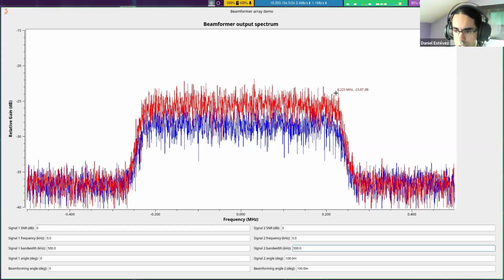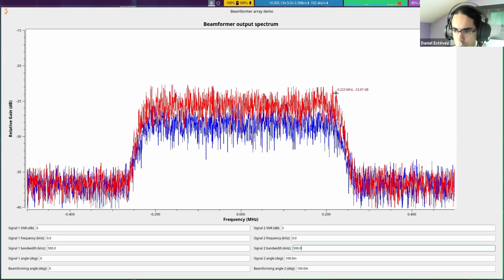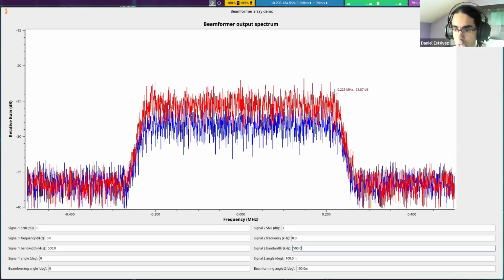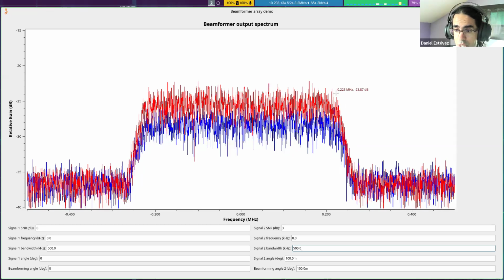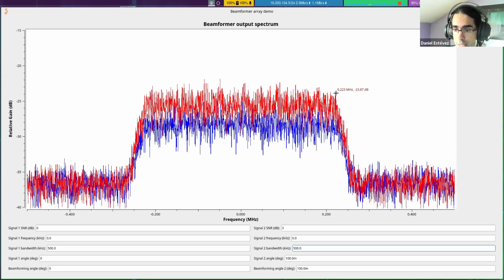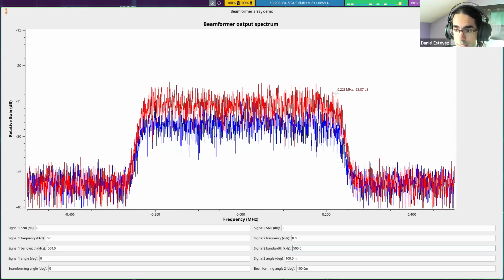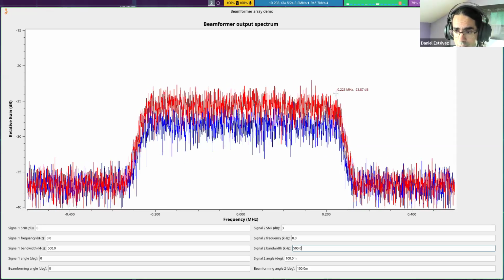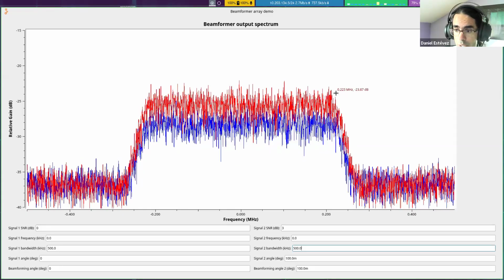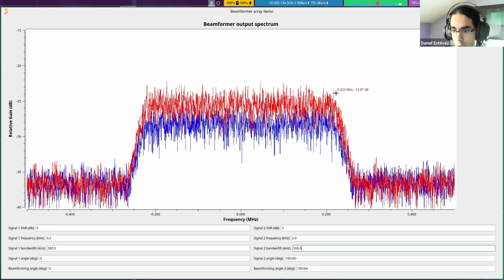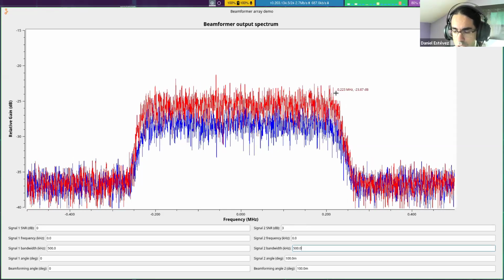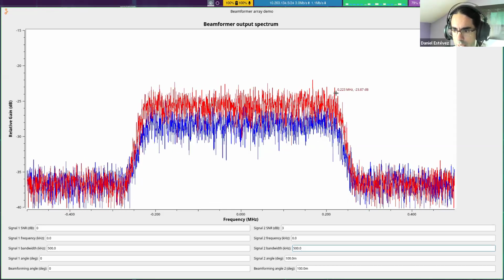So this is something which is quite interesting about beamforming. We can point these beams to just one particular location. Coming back to what Steve was mentioning about your home Wi-Fi, it has all these antennas, and one of the reasons why it has all of these antennas is because it can point beams, and it can point to, I don't know, your cell phone or your computer, and it can talk to the same devices at the same time because it's pointing narrow beams to each of them.